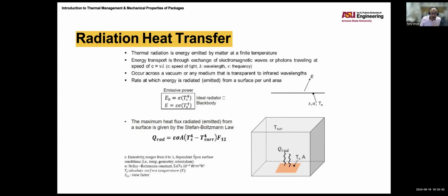Okay. Yes, the thermal metrics, you're looking at the entire package. So you can't quantify the components' junction temperatures. You can only measure or gauge the quality of the package, architecture, package design, but you cannot say anything about any of the component junction temperatures.